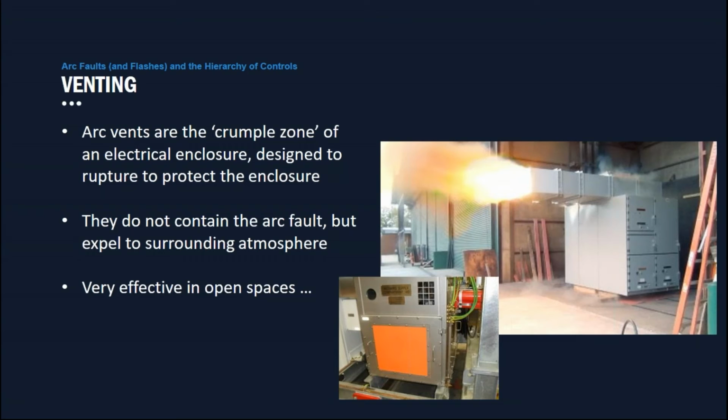But of course, we've talked about what happens when one of those vents goes off and you get flames and molten metal spewing forth. So I would suggest that venting really only works when you've got an open space. I really can't condone its use in confined spaces, but in surface installations where there aren't too many people around, I think it's a very effective solution. It's not a universal panacea.